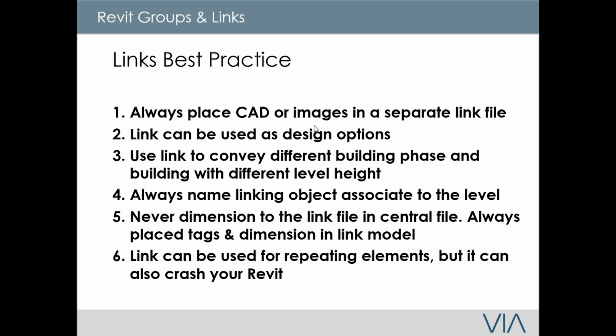Number 6, links can be used for repeating elements, but they can also crash your Revit. So before you attempt this, I always recommend doing a test. If, let's say, you're doing a door schedule, I would recommend that you first set up your door schedule, make sure the link works, and then keep at it.